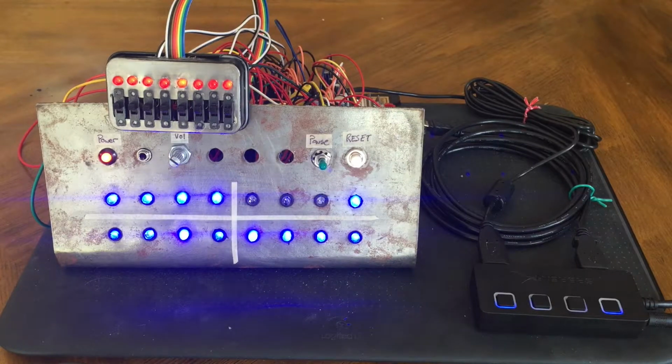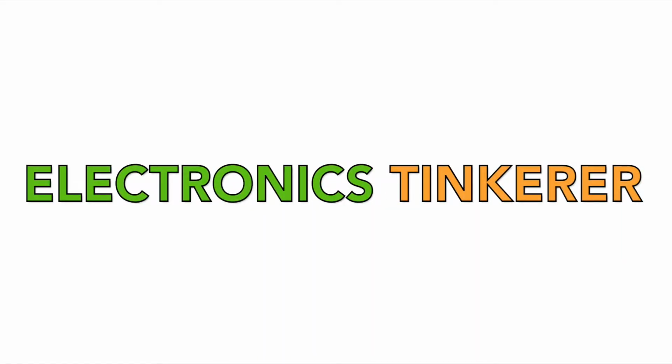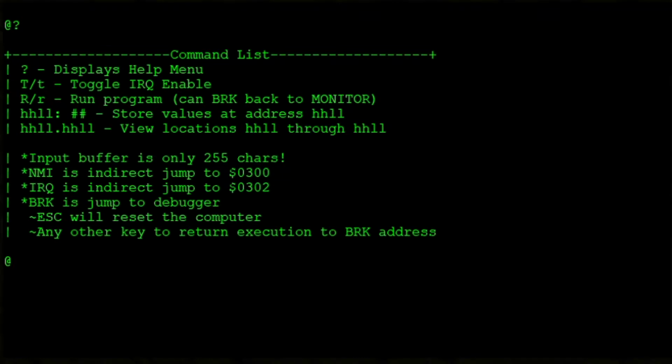On this episode of Electronics Tinker, I will be showing you Protor, my new 65C02 based computer. So here we are in PuTTY. Right now I'm running at 115,200 baud over the serial port. So if I go ahead and reset the computer, it'll bring up a prompt character, and typing in a question mark will display the help menu.